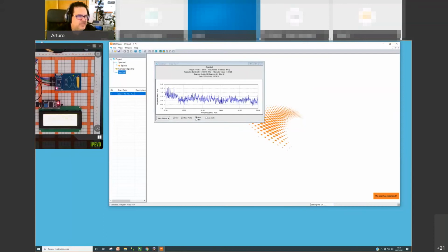Now I am expecting to measure from this device 13.56, perhaps the second harmonic, and perhaps some other energy. Look at this. The most important frequency is at 13.56 megahertz, obviously, and the other frequencies are lower. It's a very quasi-sinusoidal signal. So this is the peak that has been selected. This is 13.56. The second frequency that has been detected is 40 megahertz.